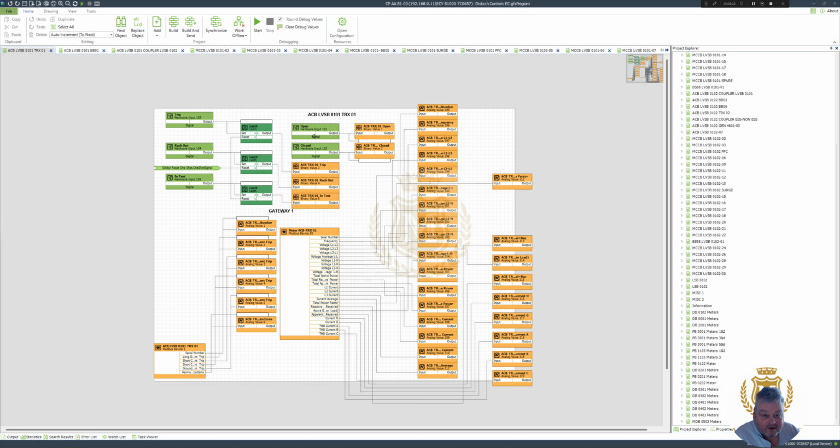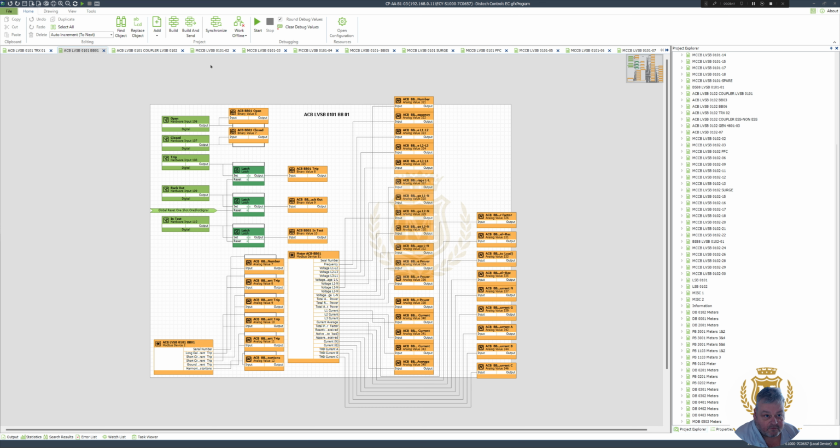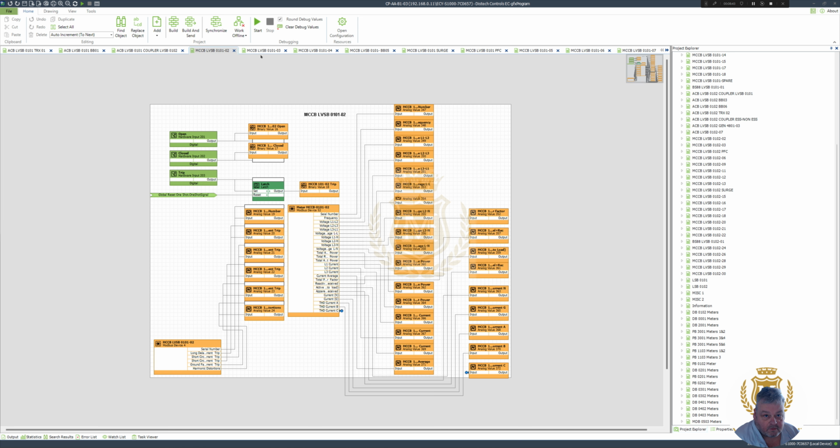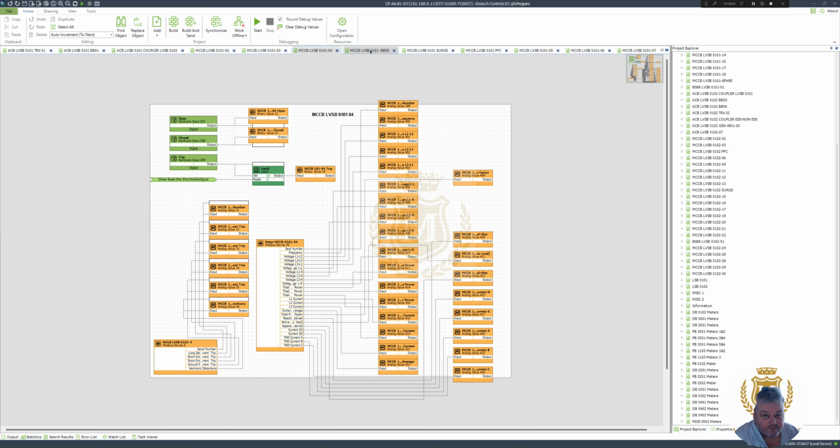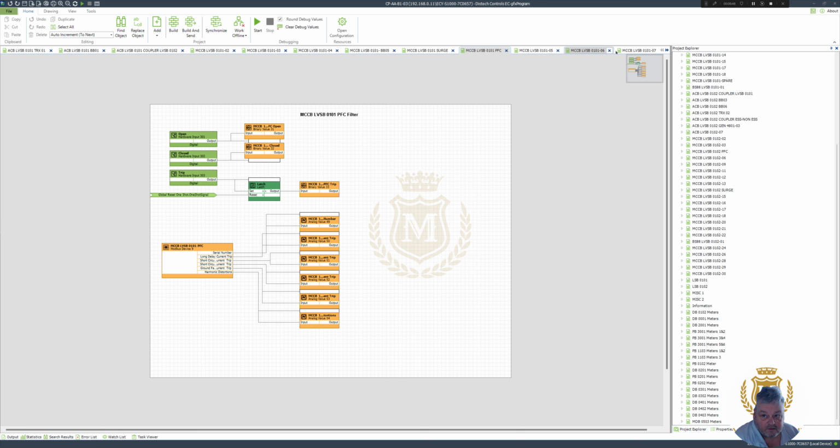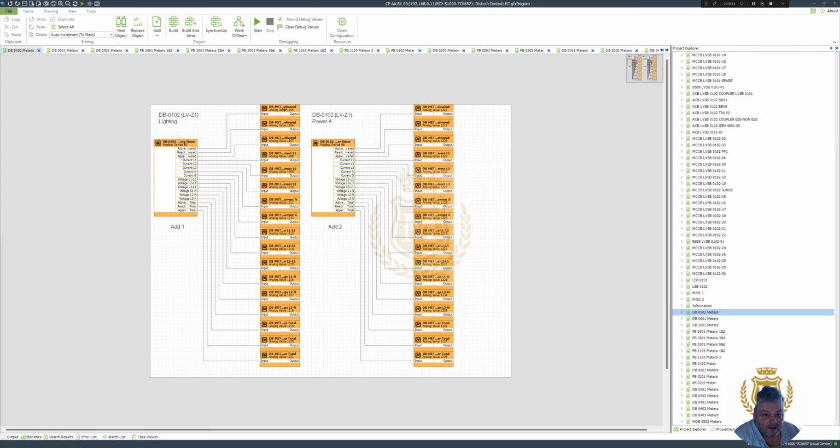So you've physically got the hardware point going into a binary value there, which I pull out, and when they've written the software, they've had to put the different name for each individual MCCB or air circuit breaker. And if we go to the meters side, let's just open up one of the meters here, and then these have had to have their own name as well for each point coming out for the Modbus.